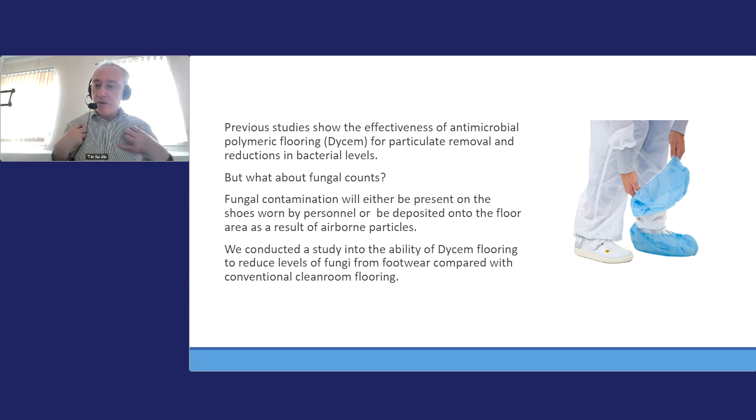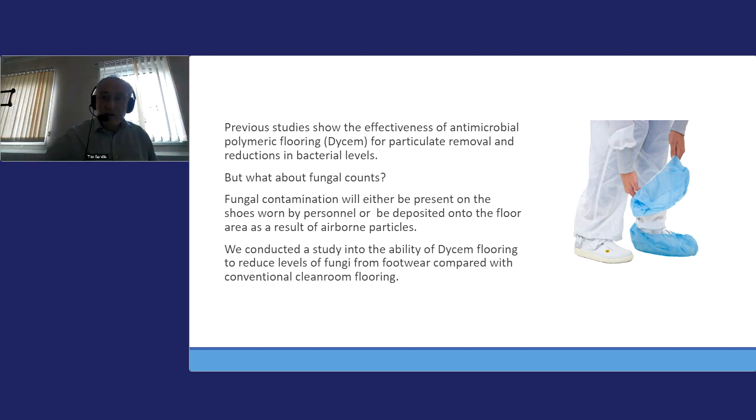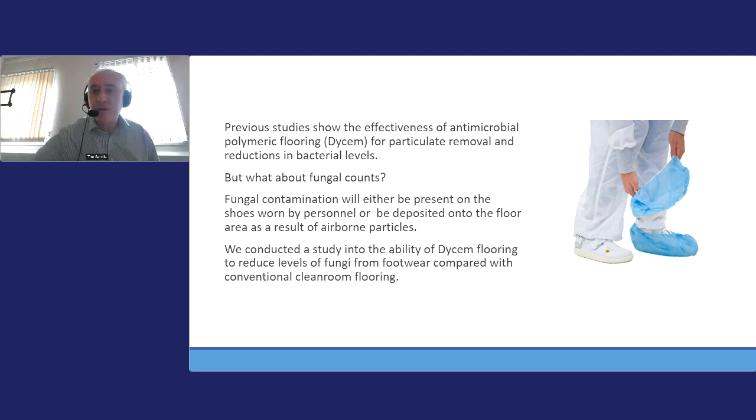What we are carrying on the human microbiome, there are elements of fungi. There's a lot of fungi associated with the as-built environment, Penicillium, Cladosporium, for example. And there are a number of fungi from the external environment that can be transferred into the clean room, Fusarium, Alternaria, also forms of Penicillium, for example. So we undertook a study, and the outcome of the study, which we're comparing Dycem flooring to vinyl flooring, was that the Dycem flooring was superior at removing fungi from footwear.